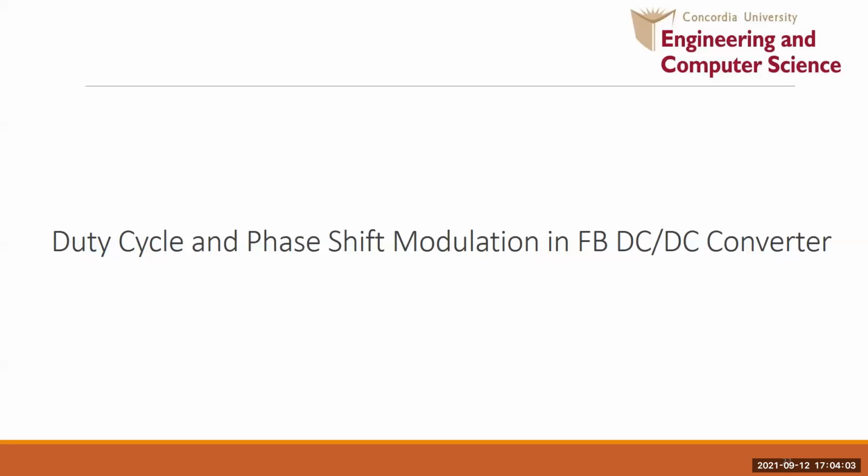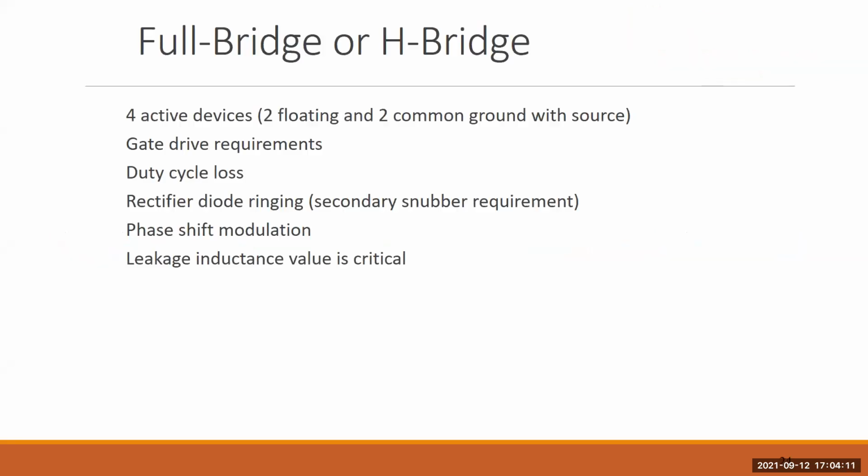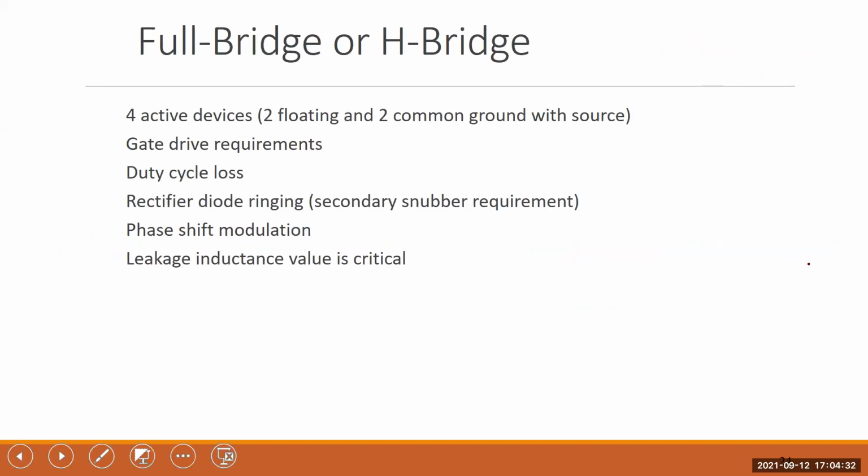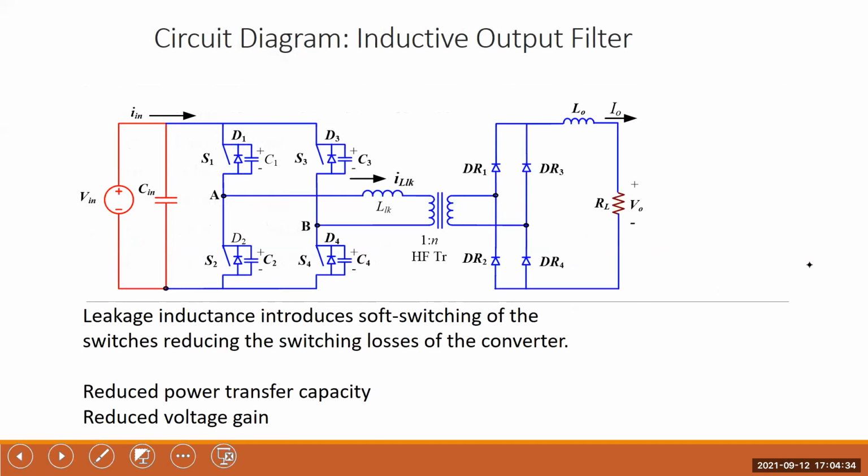Okay. Now, just coming back again. Earlier we discussed the modulation of the inverter. Now this is about modulation in a full bridge converter. For that full bridge DC to DC converter, we always talk about soft switching because of the high frequency switching, and this switching is quite high, 100K or something. Somehow different modulation can give you different performance or soft switching range.